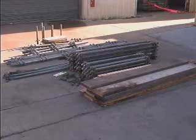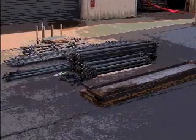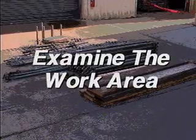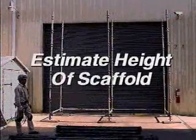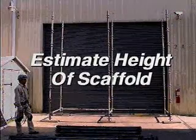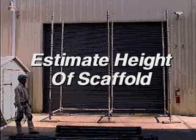Before any scaffold is erected, there are some basic preliminary steps that should be done. One of the first steps is to carefully examine the work area for hazards in order to determine where to place the scaffold. You should also estimate how high the scaffold needs to be built, so you can determine how many components will be needed.